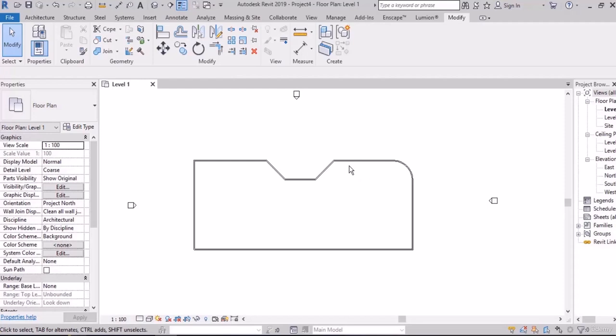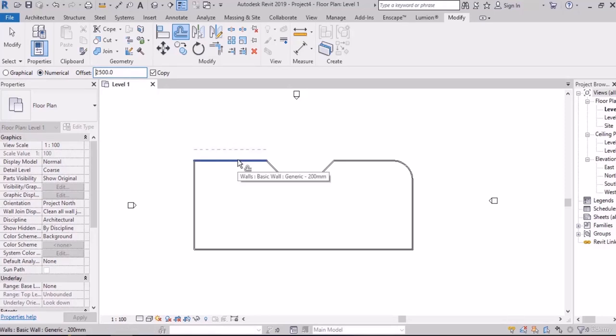When you click on offset and then you enter a number, for example 2.5 meters, you see the mouse flasher is here now. So if you want to offset one wall, then it will be okay, but if you want to tap and then click on it, it won't work because the mouse flasher is on the offsets number. So remember this in all commands in the Revit. If the flasher is still in the offsets number, the tab will not work. You need to click once and then it will be free. Then you can use the tab to do whatever you want to do.